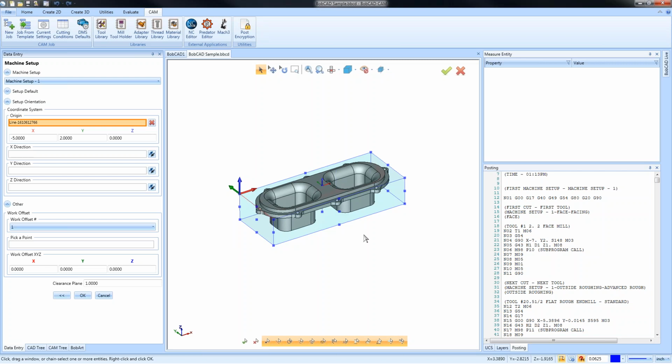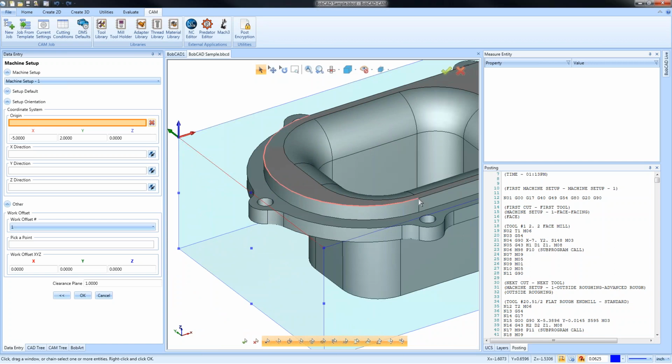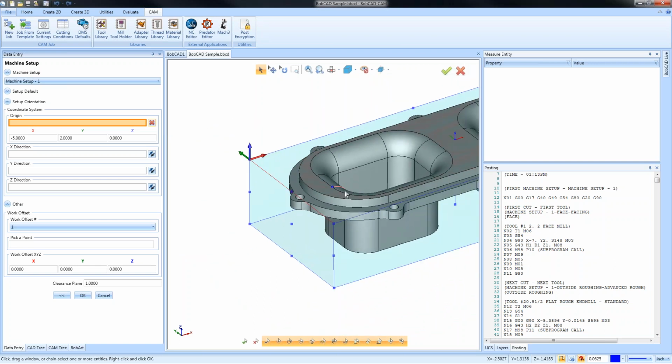So we put up a bounding box on the screen for you. If you don't want to use the bounding box, you could pick off your surface edges, okay? So I could grab a surface edge here, and you can see some of the snap points come up with surface edges. You could also utilize some wireframe, and then you'll get all the snap points. So you can pick a 0 wherever you want, whether it's from a surface edge, whether it's from the bounding box that we create, or whether you create some additional wireframe.